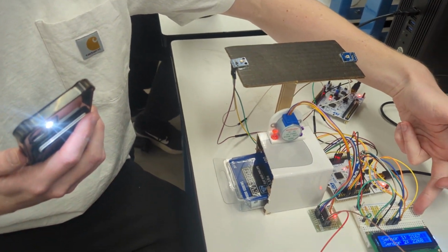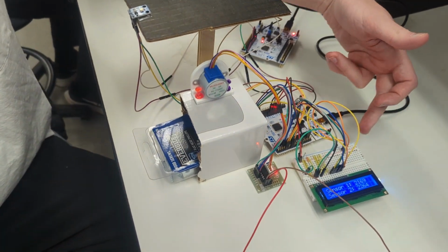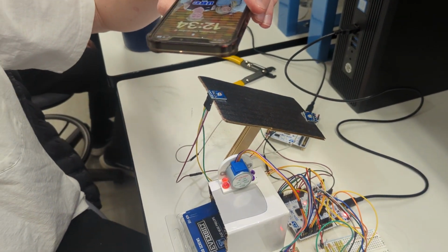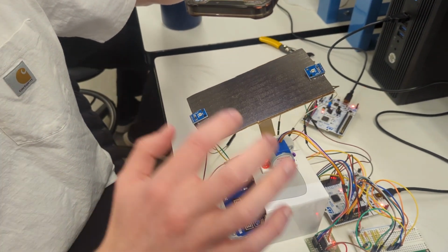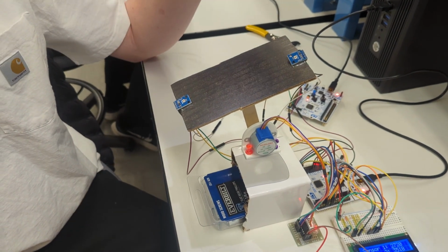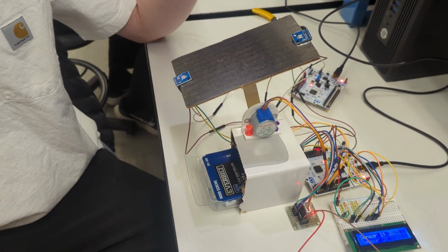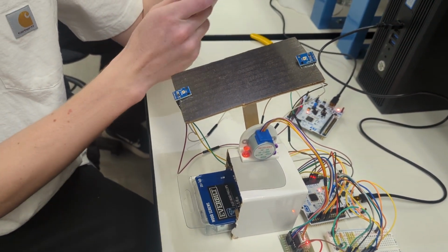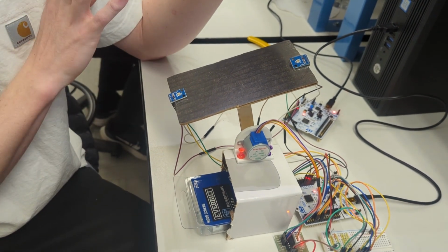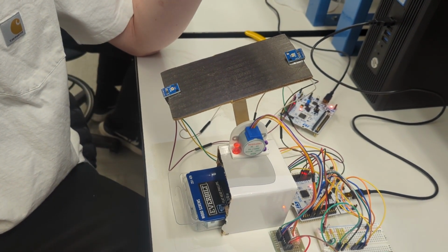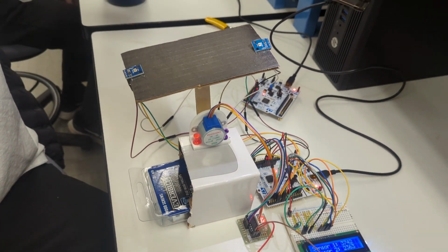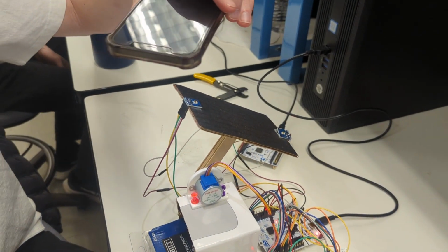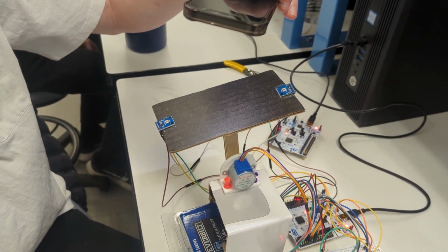Like Every said, these sensor values are being displayed once every second. And then if we shine a light on this end of the panel, it'll track that way. Same thing if we go that way, and then it'll stop once the values on the LCD are within 1000 lux of each other, meaning that the light is concentrated in the center and not dominating one end or the other. This ensures that the light is always hitting all of the panel and maximizing the amount of electricity that can be generated. So once again, if you go this way, it'll tilt there, stop once it's within 1000 lux, and same if you bring a light that way, it tilts there.